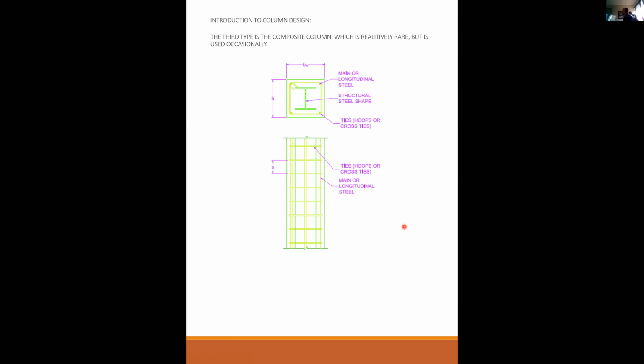In the Kobe earthquake, the Japanese construction used these, but they terminated the steel and just let the concrete column go up above the portion where the steel was, and that caused some problems. But in US construction, I guess we use them, but I've never seen one. So that just kind of shows they're fairly rare.